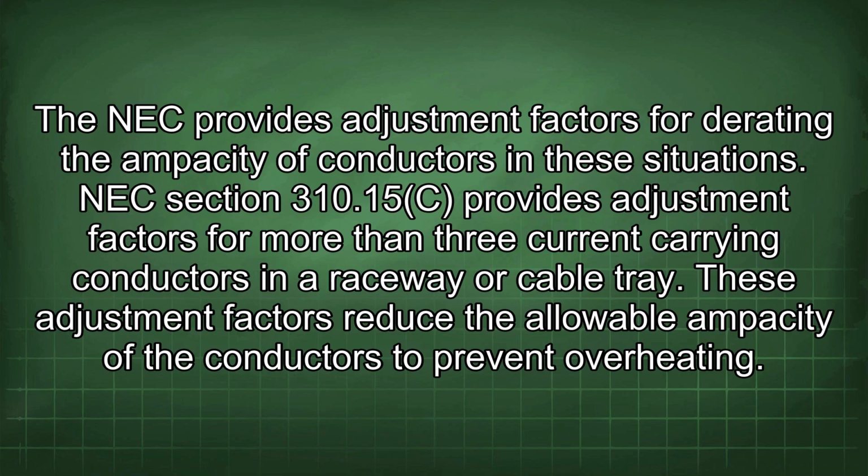NEC Section 310.15(C) provides adjustment factors for more than 3 current-carrying conductors in a raceway or cable tray. These adjustment factors reduce the allowable ampacity of the conductors to prevent overheating.